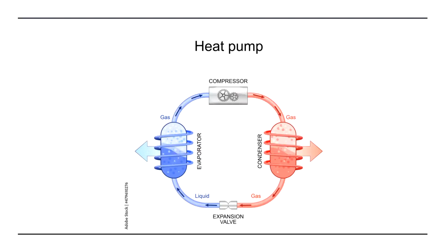All right, so to give you a visual here, I found this image off the Adobe stock, and it is the simplest way to take a look at a refrigeration system. So remember, I said the compressor is the physical heart of the system, and its goal is to take a vapor refrigerant at low temperature, increase its temperature, and squeeze it down into smaller packets of vapor and send it to the condenser where it can reject the heat.